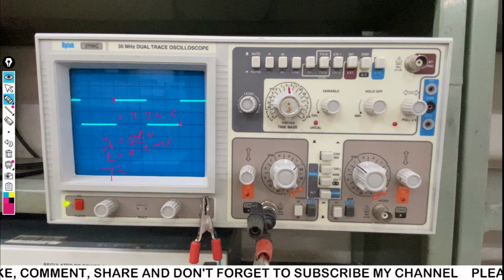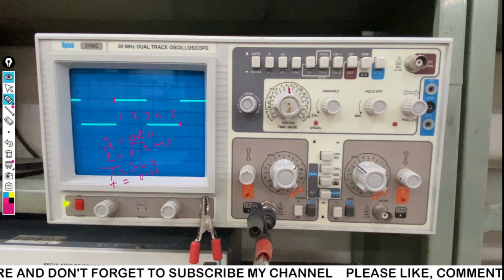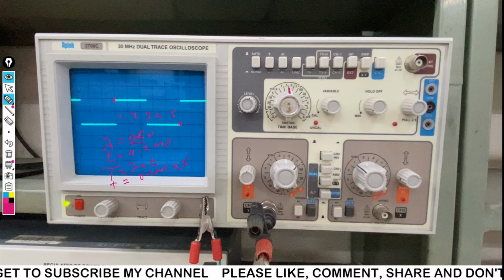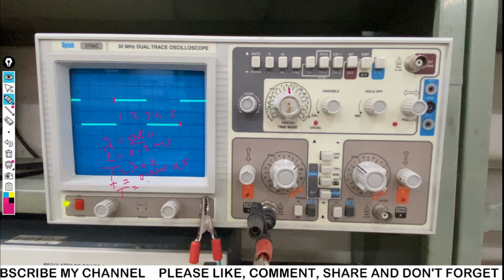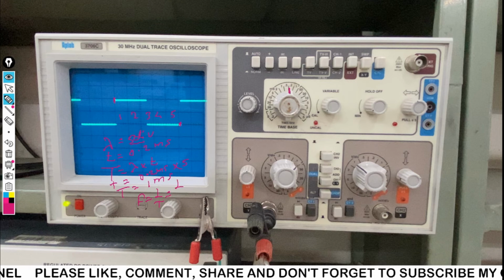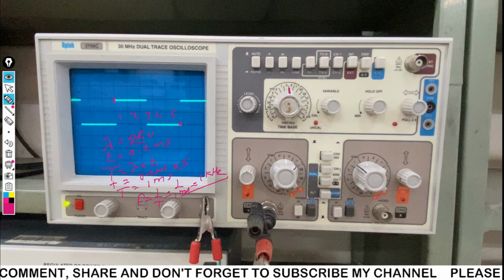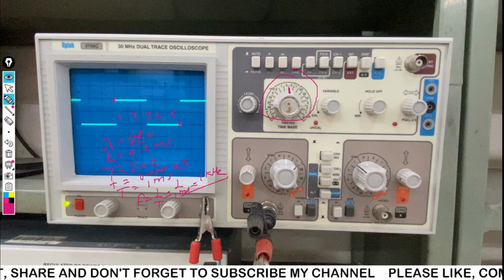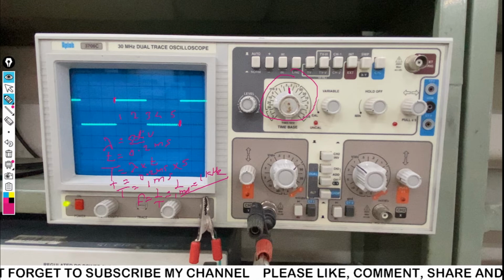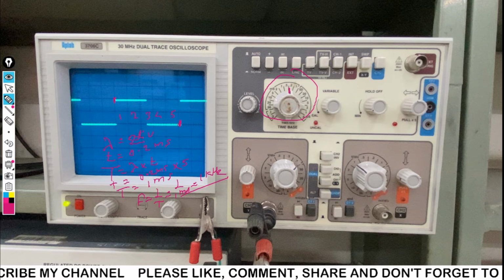You can find capital T from it, so lambda into small t. So T is equal to 0.2 millisecond into 5. I have already cancelled the division, so T is nothing but 1 millisecond. If I take the frequency of it, 1 upon T, 1 upon 1 millisecond, that will be equal to 1 kilohertz. In this way, by using the time base knob and the wavelength lambda, you can calculate a frequency. So this is the way to calculate amplitude and frequency in the case of a CRO, cathode ray oscilloscope.